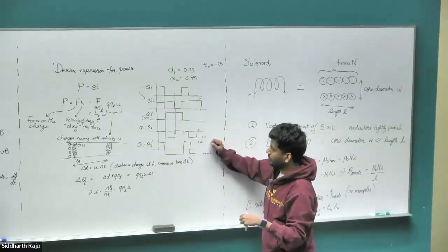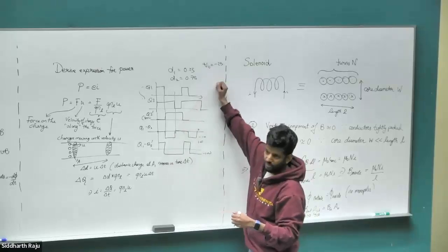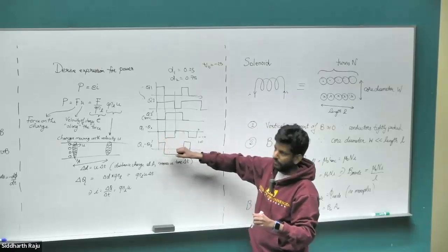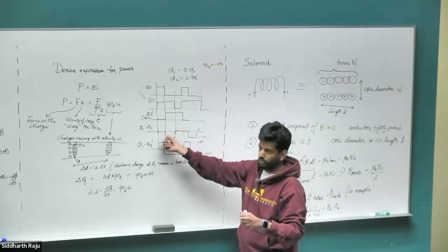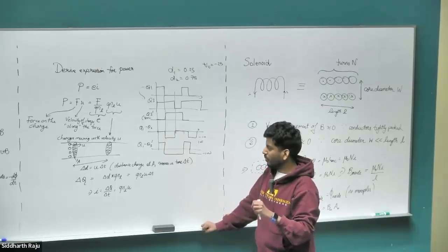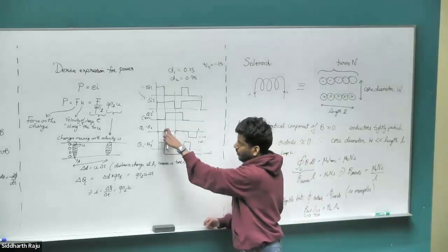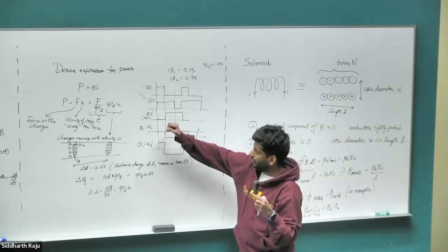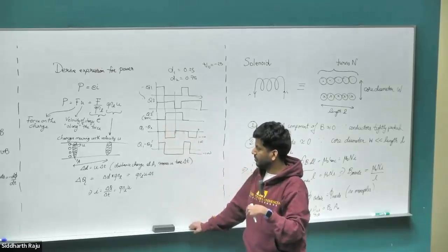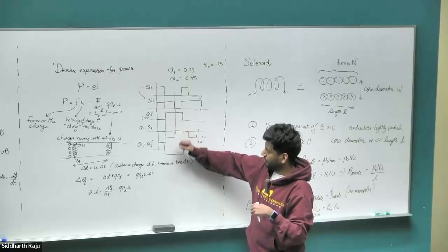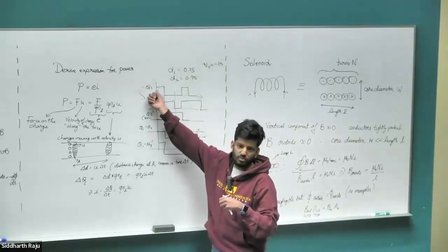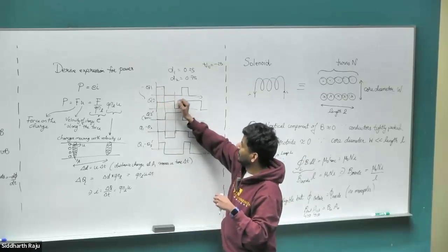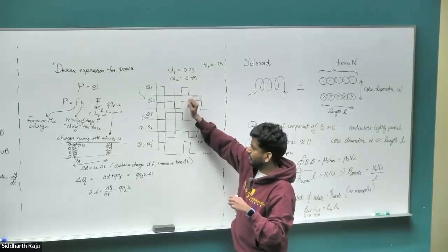This is absolutely fine too, because when we do the average, you would still end up with the same negative 25 volts. But the only problem is here you're switching from a voltage level of 100 to negative 100, while here you're limiting your switching from 0 to negative 100. So most of the time you would prefer to have a lower switching voltage level, because that would reduce your THD and your dV by dt, and you would end up putting less stress on your components as well. So there are advantages to keeping it in this form rather than this form. That's why we start off Q3 synchronized with Q1. So you make sure that the turn on happens at the same time. The turn off can be out of whack. All right, so that's the reason we went with this method.